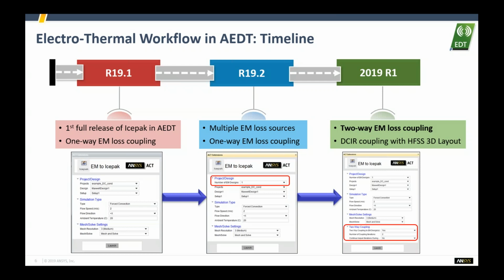As opposed to a structure tree, which traditional CAD or mechanical engineers are familiar with, the 3D Layout version opens up a different interface that takes ECAD instead. The models are presented layer by layer, with vias and traces. So that's more friendly to electrical engineers.